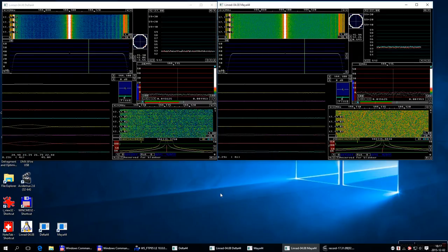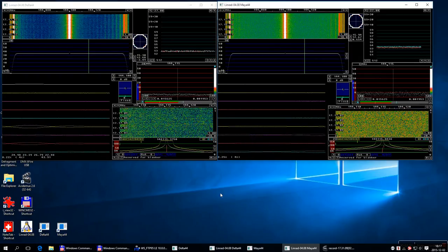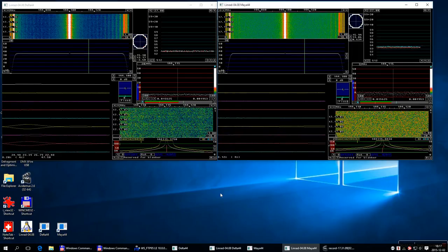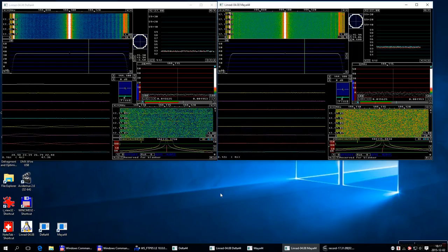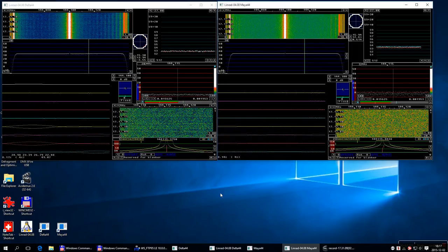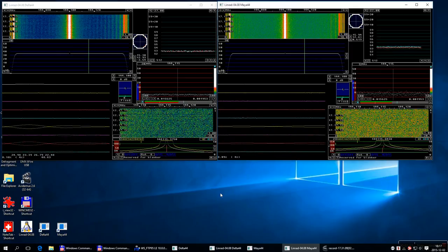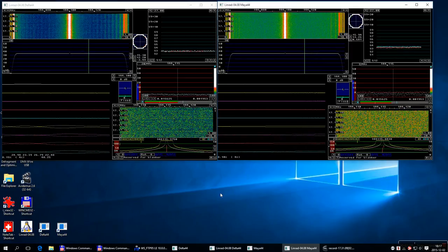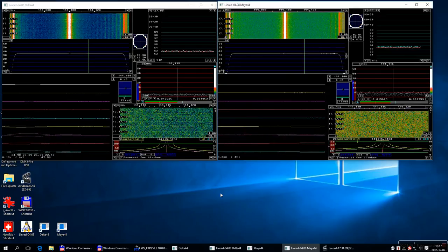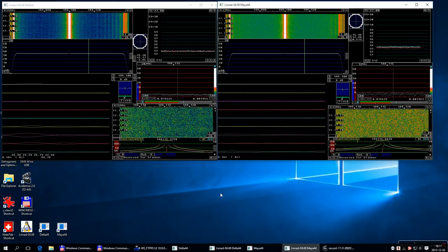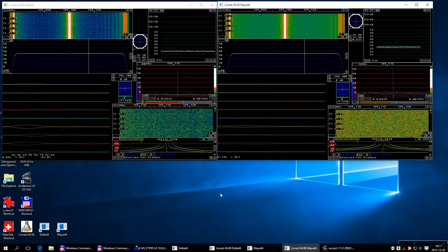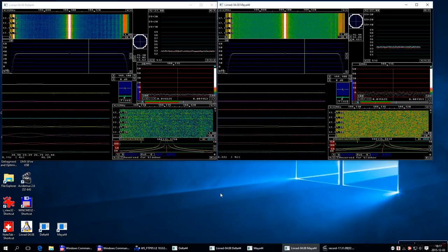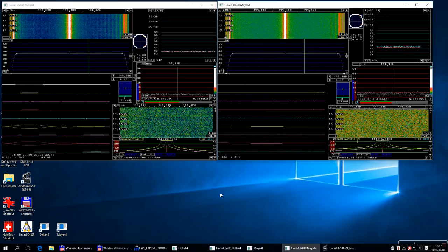So with a good LNA that didn't add any noise at all, but would amplify by those 12 dB, the noise floor would be at S1, which would be the IARU recommendation. Now, that recommendation doesn't make sense at all, of course.